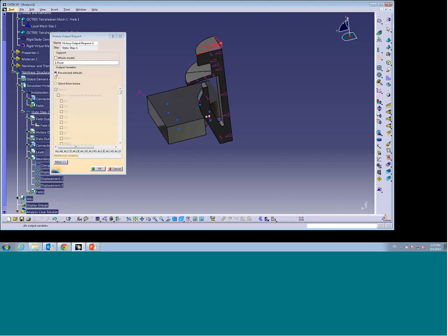Okay. Pre-select defaults. I don't need pre-select defaults. I actually need to select what I want to have, and this is reaction force in Z direction. Okay. So I'm going to scroll down looking for reaction forces. There are strains, plastic strain components, and all that goes in elastic. Logarithmic, but I'm looking for reaction forces, translations, forces, and moments. Okay, so reaction forces, and because I need this Z direction vertical, I'll just check RF3.